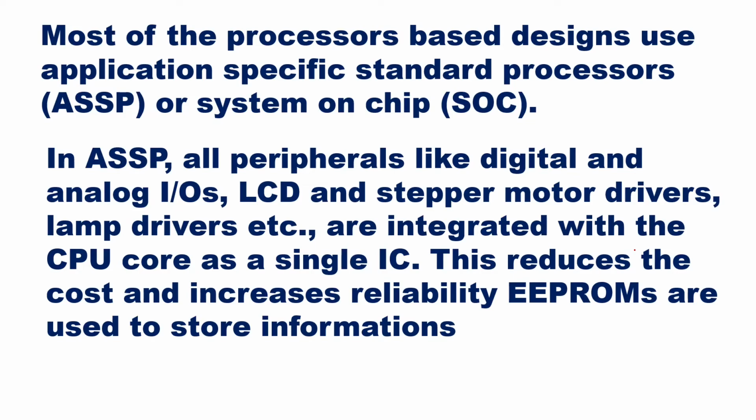Most of the processor-based designs use an application specific standard processor. So it is an application specific IC what you're going to use here. It's a system on chip. It can also be called a system on chip. So on a single IC, according to your features, you are going to design an IC for the particular performance of the vehicle. Okay, so that IC will be responsible to show all the indications on the instrument panel.